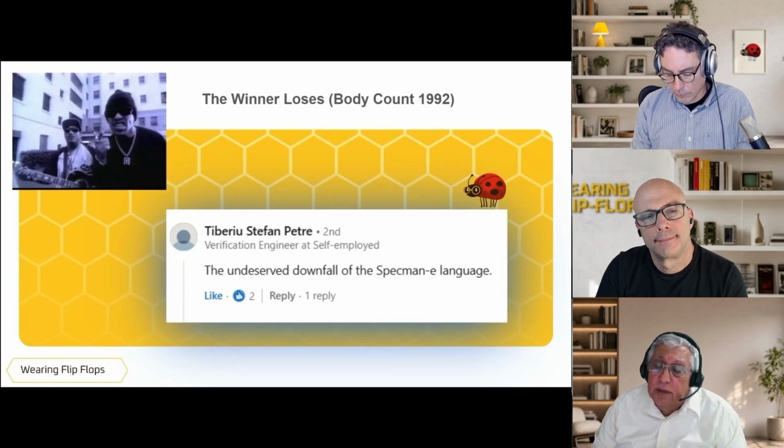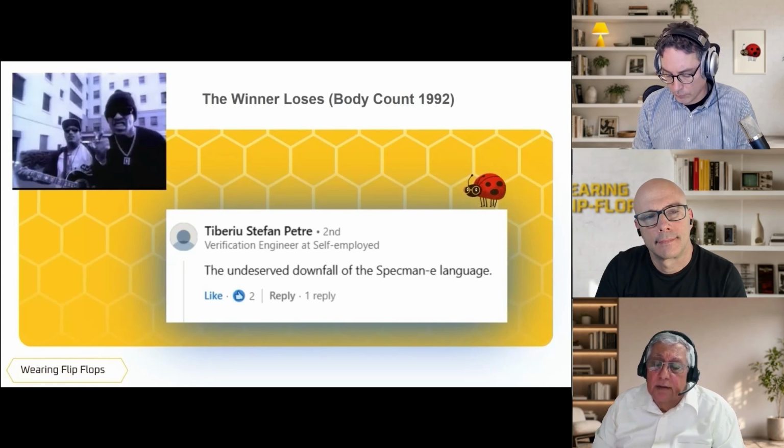You want to change the scenarios that are injected. So, can you say a few words about what is aspect-oriented? Aspect-oriented enables one person to actually extend a struct type without inheritance. It means that I can go to any struct that is defined in the verification system and add to it, whether this is data or a constraint for random generation, or even modify a method.